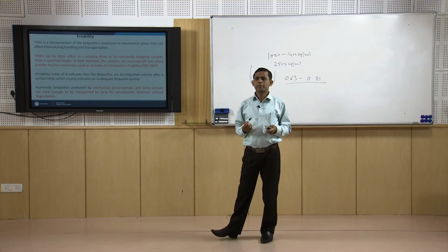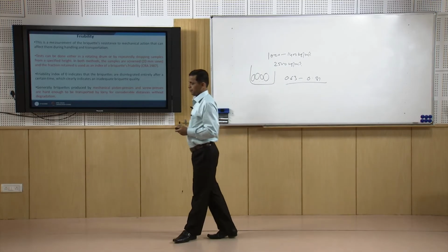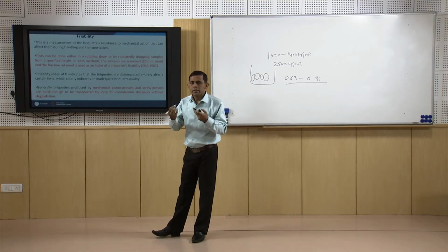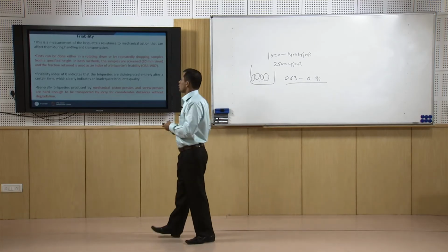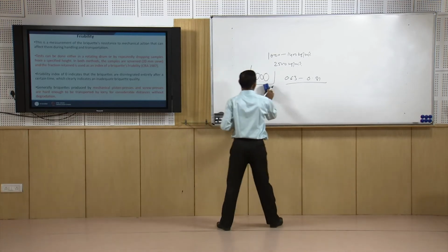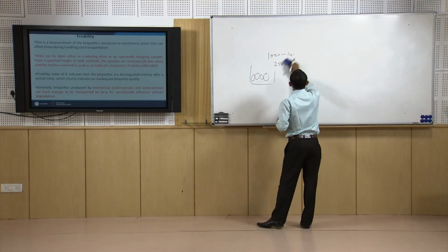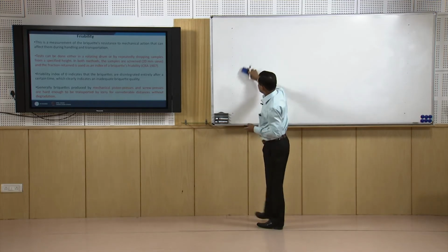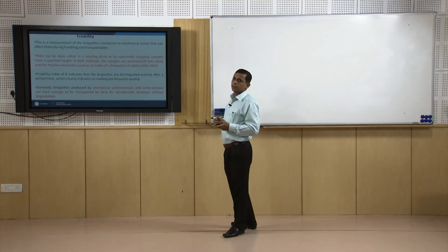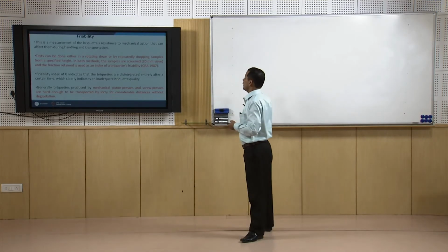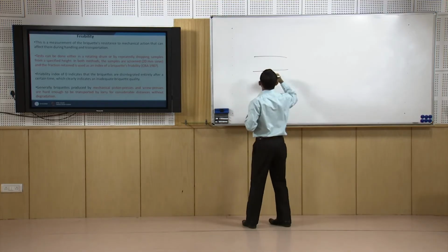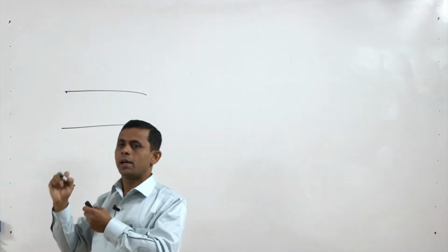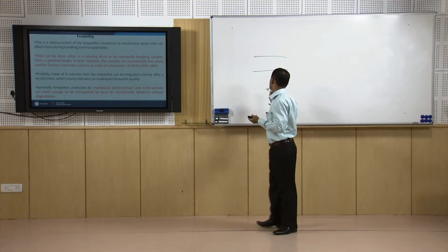Now, we will discuss friability. So, what is friability? That is the property of resistance to mechanical shock. If some material is under mechanical shock, how resistive it is to it, that is related to friability. So, how can we measure the friability? For measuring friability, we can use a rotating drum. We put the material inside the drum, give a certain RPM and continue for a certain time period, then we collect the material